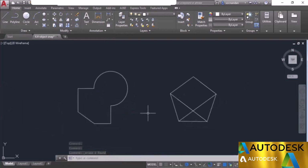You can access these object snap options directly from the right contextual menu as well. So in the situations where there are plenty of object snap points and it becomes a little difficult to select the exact snapping point directly from this object snap menu, then you can use the alternate method, and that's the right contextual menu. For example, here we have this circle. Now let's make a line also in this case. So I'll click at this point, quadrant, and I'll join it with this point.